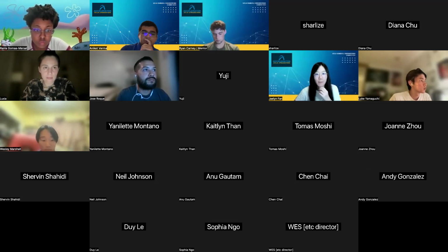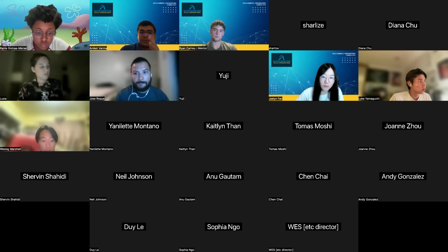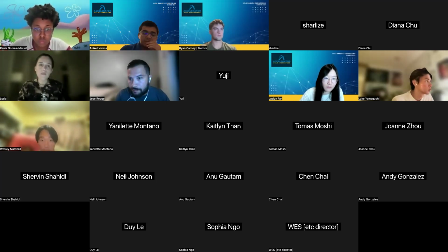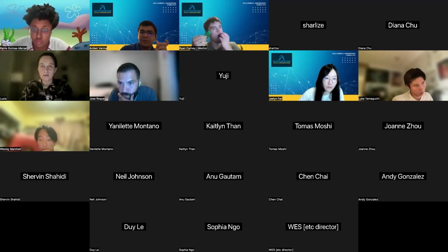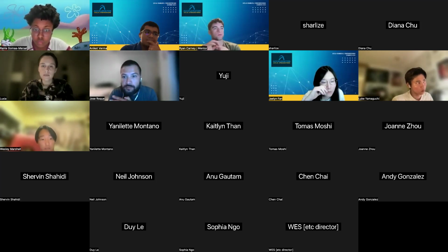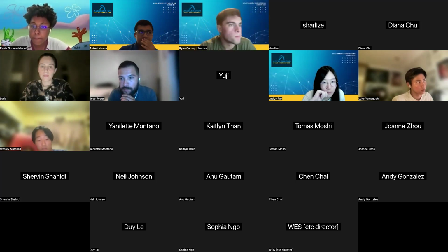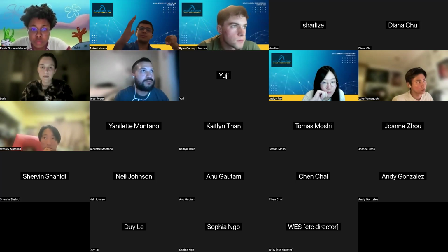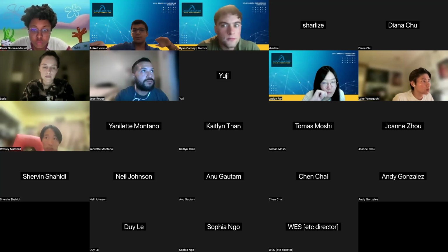Before I show you guys how to do it, I'll just talk you through it right now. How I did it was I realized that the edge of that little weird funky shape in between has a gap of C for the outline. So that means it has to be C everywhere, and the curved part, which is parallel to this circle, has to also be from the same center point as where you drew your previous circles. So that's how I drew one of the edges, and then I drew a straight edge on top, and then I did the same for the inner circle, and then I did one for the bottom.